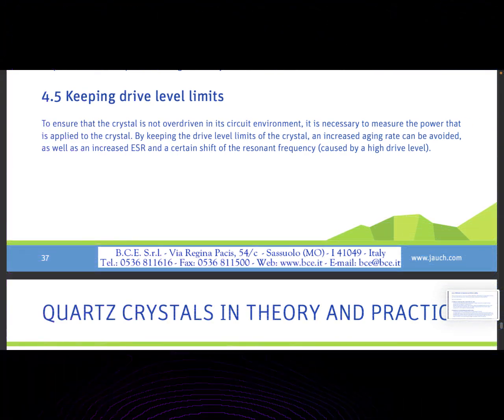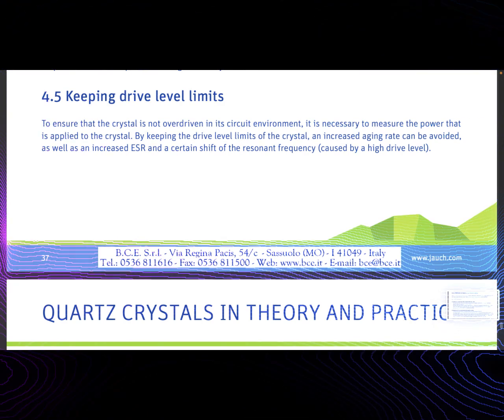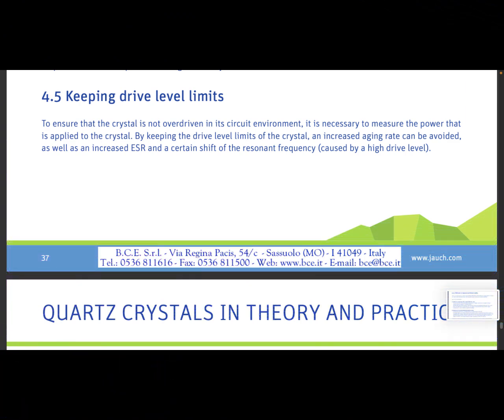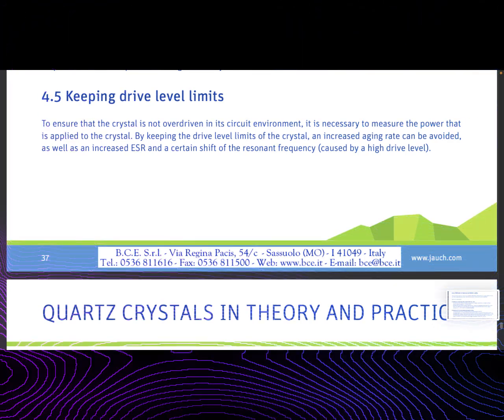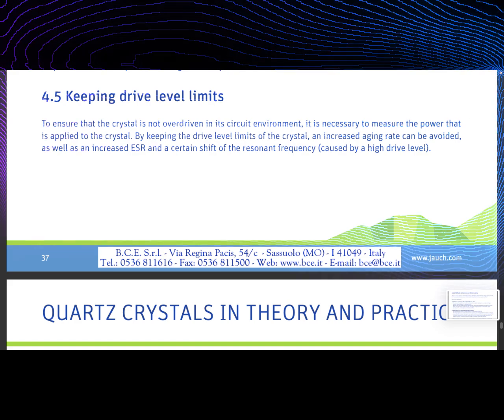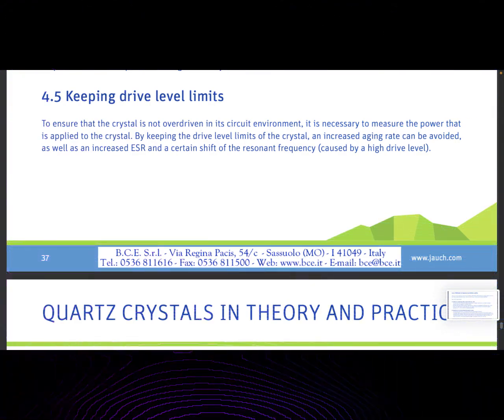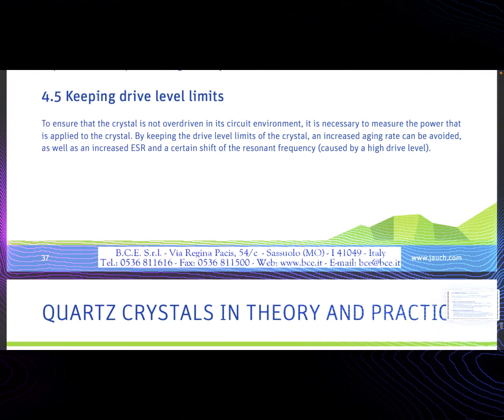It should be noted that due to the cubic function that is associated with the AT cut angle, the resulting FT characteristic is more stable than most of the other cutting angles, which often show a parabolic temperature characteristic.